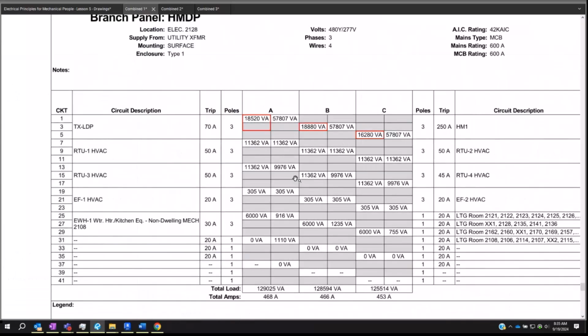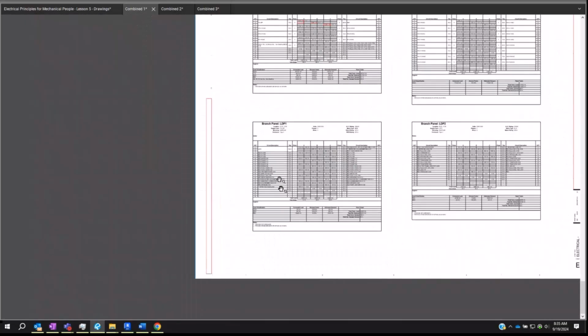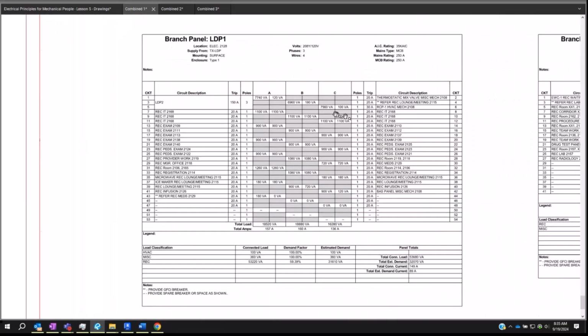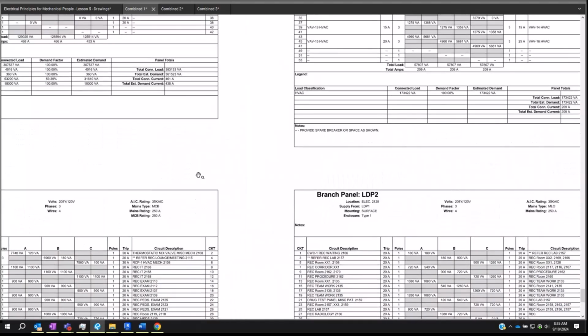And that's a trick. If you've got too much current on phase A, and you're like, hey, I can move this off because I'm really low on C phase, instead of moving stuff around here, come down here and move it because this is all single phase loads. Gotcha. So yeah. I don't know what else. See any massive examples.